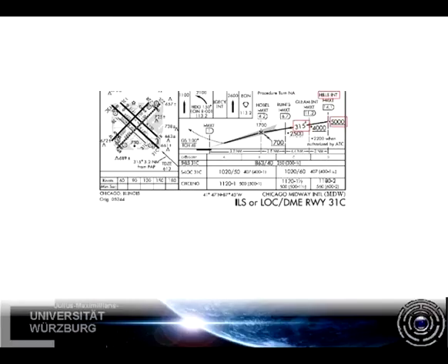We shall cross Hills at 5,000 feet and turn to the new heading of 315, following the ILS, and start descending. The next waypoint is Gleam and may not be crossed below 4,000 feet. After that, it's Runs with 2,500 feet above sea level and 6.7 DME.